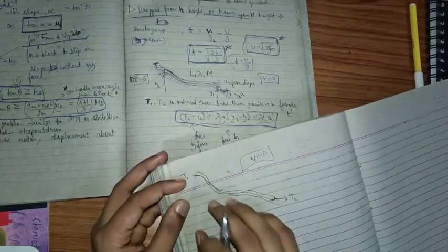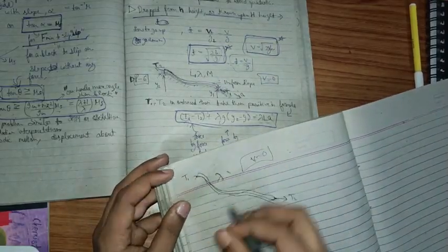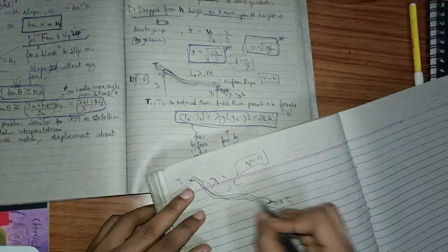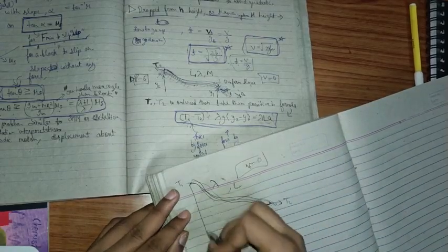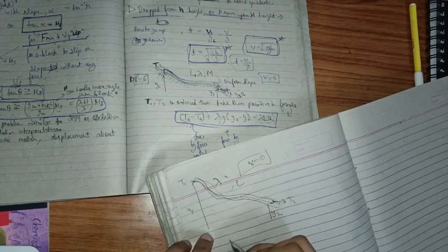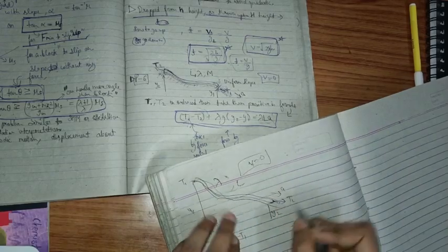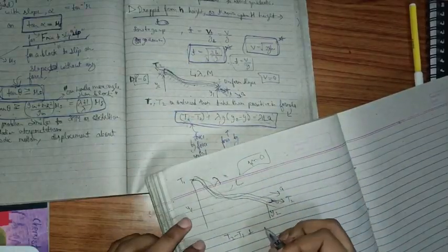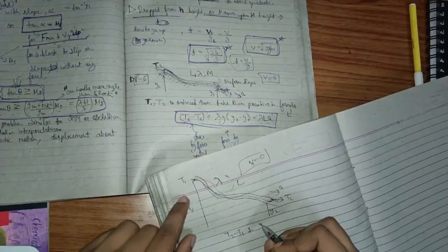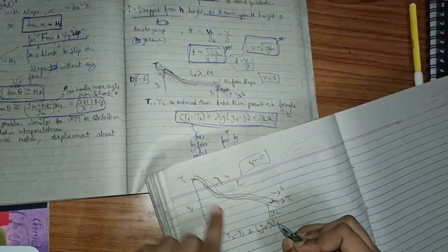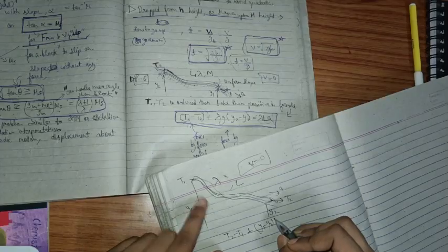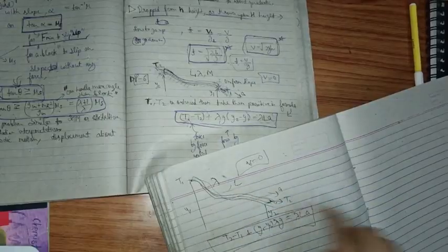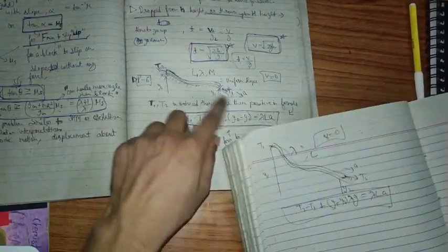It has uniform mass density lambda, and the total length of the rope is L. Let's say I'm pulling in this direction, with heights y2 and y1. Then I take T2 minus T1 for the acceleration in this direction, plus gravity also applies a force in this direction, equivalent to (y1 minus y2) lambda g, and that equals lambda L times the acceleration of this body along the surface.